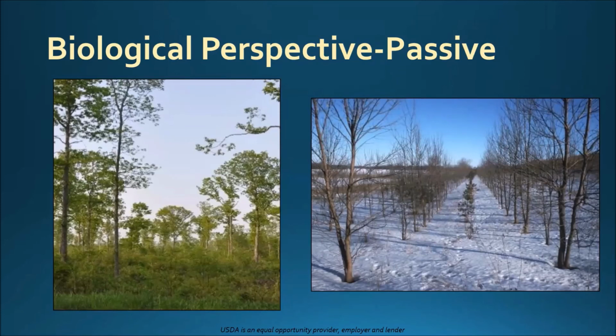A fully passive situation, the site is just begging to be a wetland. You know when you're out there that this is just wanting to be a wetland. The cessation of all agricultural practices will result in the natural revegetation of the wetland species. This is often the case in floodplains, as stated earlier, where drainage systems are not what's impacting the hydrology, but rather the flood patterns themselves.